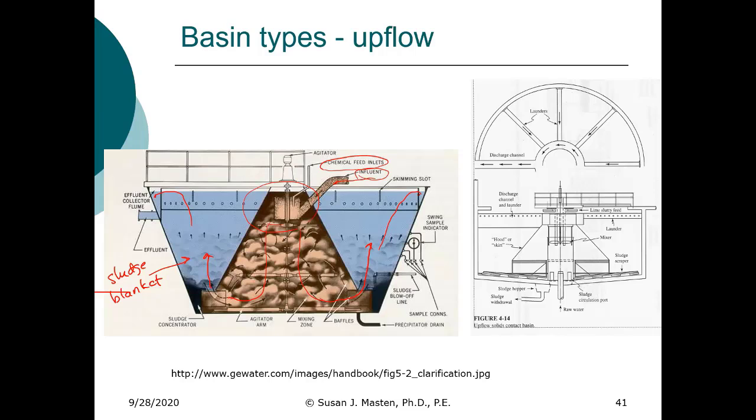which in most cases would be a filtration system. So in East Lansing, what they do is they use upflow clarifiers as the primary stage 1, and then they actually have ferric chloride to remove some turbidity because they have water coming in from their sludge drying ponds. So they use ferric chloride, and then they have a second sedimentation system. So that's a conventional sedimentation basin, and then the water flows into filtration.